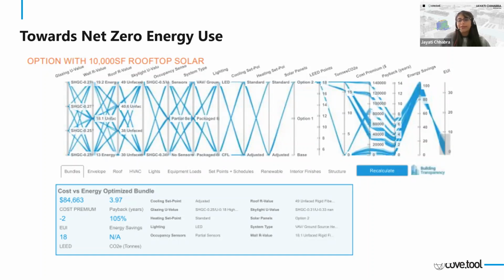And also, while building orientation had minimal impact, as we saw on the energy use, it may have an impact on the effectiveness of rooftop solar. So if they go for it, building orientation should be considered again, as it impacts the surface radiation intensity and renewable energy production for reducing overall energy use and reliance on fossil fuels.